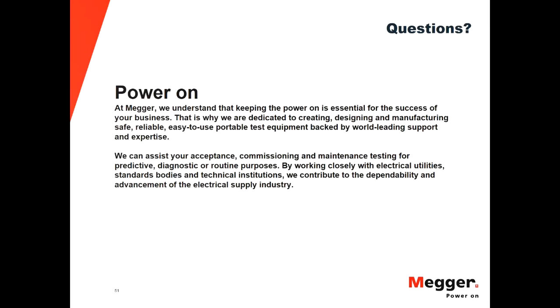All right, next question. Please share some details on load duty cycle versus battery duty cycle. Well, from this question, I guess what the person is referring to as the battery duty cycle is what the manufacturer can offer on the battery. The battery will have these tables, and it will show what constant currents the battery can deliver. And that is totally different from the load duty cycle that is going to be happening at the substation or the facility where the battery is connected.